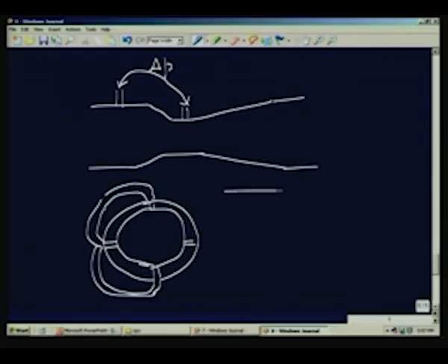So, if you look at the cross section of the pipe, the pressure taps will be there like that, and on the wall here, on the periphery, all of them are connected to the same port or the same hole, which is going to be connected to one arm of the pressure difference measuring device. So, here also you will have several holes on the periphery, all of them connected to this tap, and here I have several holes which are connected to this tap. So, it is the average pressure around the periphery which is normally measured in the case of an installation like this.